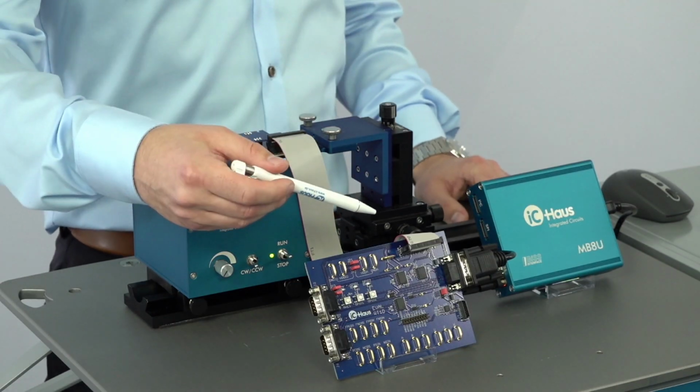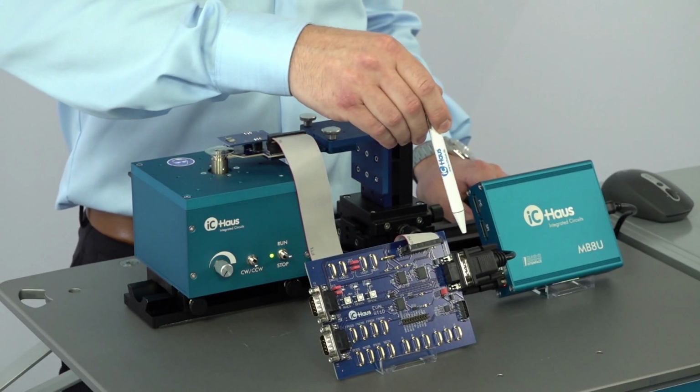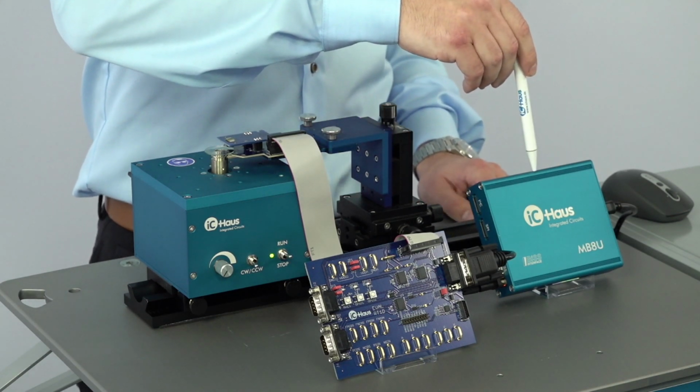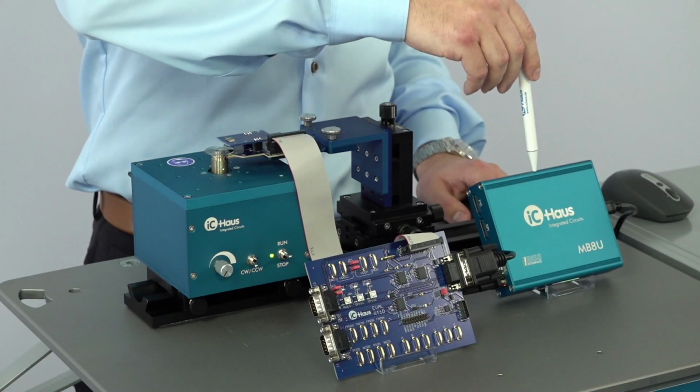Then the sensor board is connected to the adapter board, as I have showed, and via the sub-D connector here, it is connected to our latest BiSS to USB adapter, high performance BiSS to USB adapter, the MB8U. Since I want to show you a little bit of an accuracy measurement, we go into a BiSS chain with this reference encoder inside the motor. That's it for the setup.